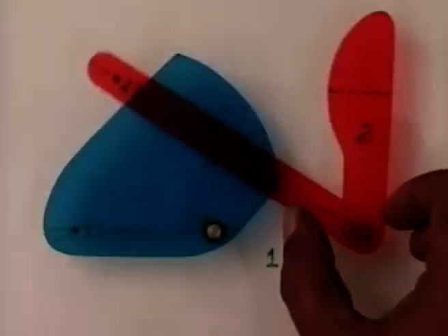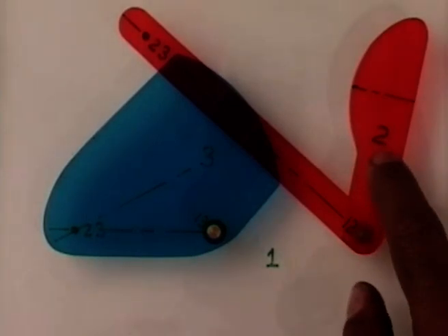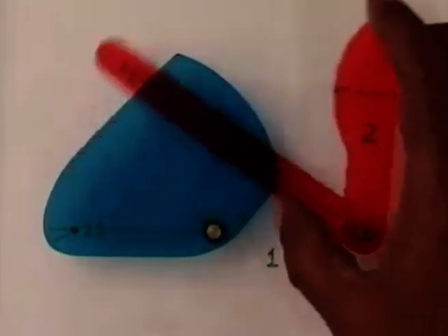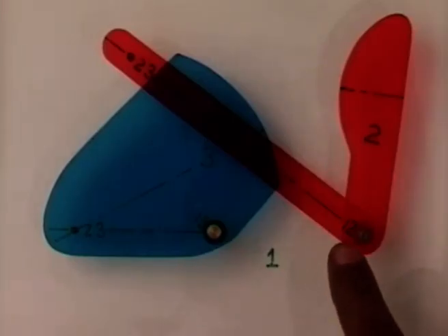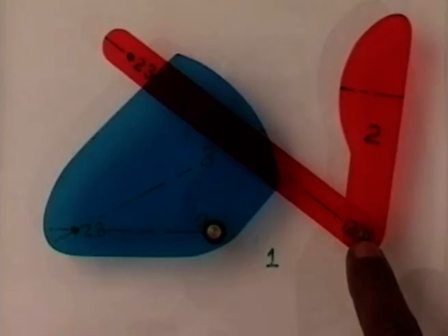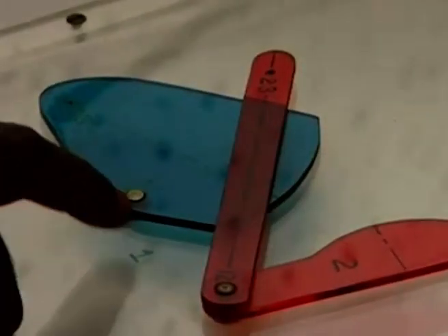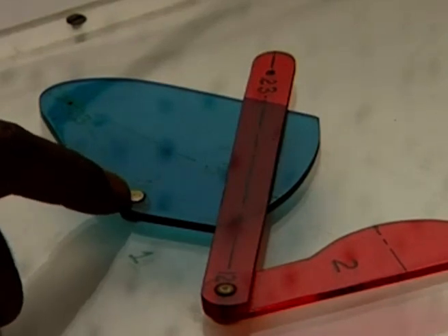In this model, as we see, we are talking of three rigid bodies in relative motion, namely one, which is the fixed link, two, this red body, and three, that is this blue body. So now 1 and 2 are connected by a revolute pair here, so immediately I locate the relative instantaneous center 1, 2 at this point. Similarly, body 3 is connected by a revolute pair with 1 at this point, I consider this as 1, 3, the relative instantaneous center 1, 3.